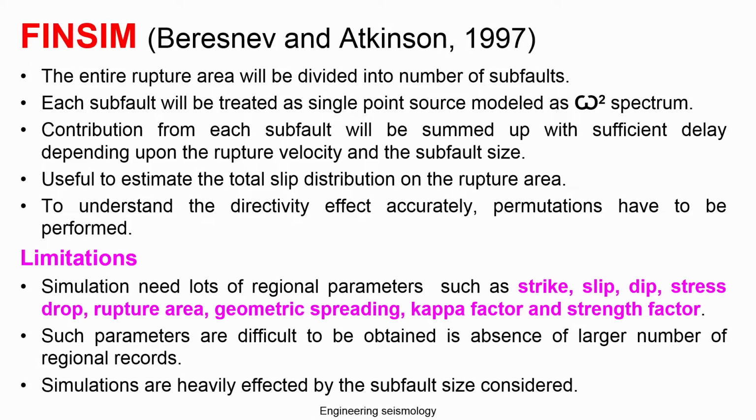Then another one is the FinSim model. The FinSim model was developed by Beresnev and Atkinson in 1997. As I said, the entire rupture area is divided into a number of subfaults. Each subfault is treated as a single point.